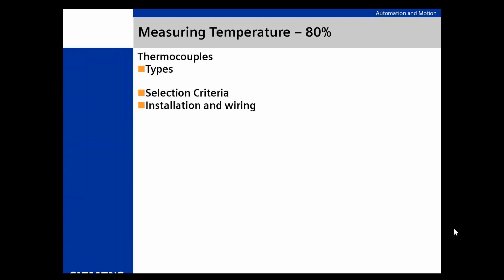I've got a bunch of sensors out there that are in the wrong place, the wrong range. They're not wired right, so I'm getting a lot of extra effect, maybe bad wiring, maybe noise. The system doesn't have a crystal ball. It's just going to take that information with the assumption that it's correct, run it through the algorithm, and give you an output to control. If that's okay, the expectation is it's going to control. It's not. And you're not going to tune that out either. And we're going to talk about that.